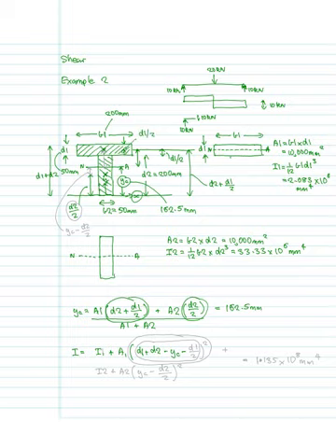So if we did that, D1 over 2, and we squared all of that, that would give us, using the parallel axis theorem, the second moment of area of the first area around the centroid. So that squared term, or perhaps more specifically what's inside there, is going to be this distance here, the distance of the centroid of the first area to the neutral axis.